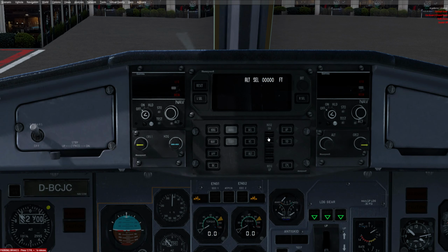This is your pitch wheel, autopilot, yaw damper, and couple. You can go pilot, co-pilot, or both together under 1,200 feet. That can be useful. And indicated airspeed is useful for climbing out, and descent, vertical speed is the one that you want to use more often. This indicated airspeed on the climb out is, you aim for about 160 knots at a rate of climb of 1,000 to 1,500 feet per minute.